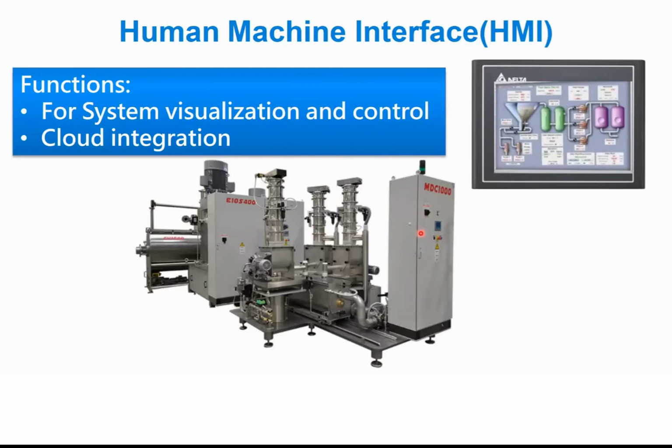And besides visualization, you could also use the HMI for control. So you could have a button on this screen, and just clicking on the start button, this machine starts running. So that's the basic use of HMI. I also have this advanced function in our HMI, cloud integrations. With this function, you can connect your smart device, a smartphone, iPad, iPhone, Android devices, your tablet, to the HMI, and you can remotely control any controller, any devices that is connected to the HMI.